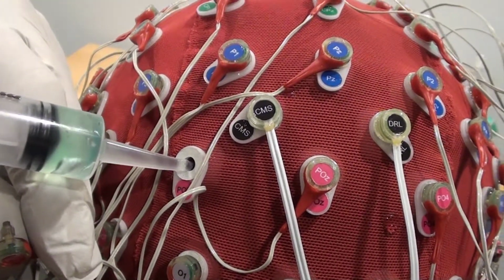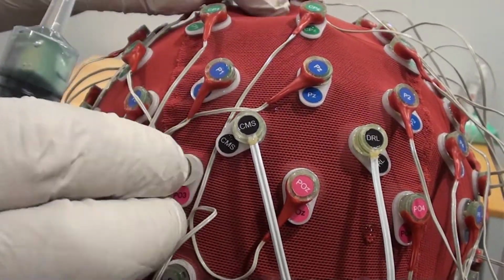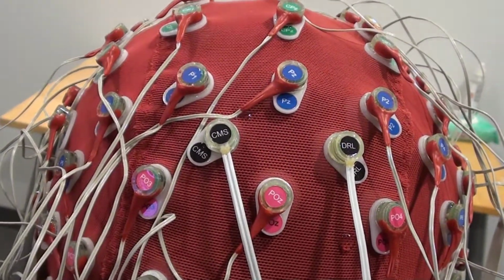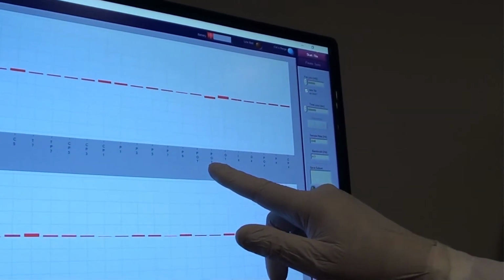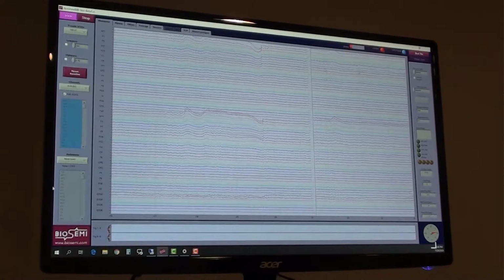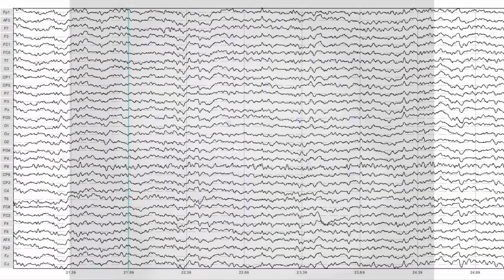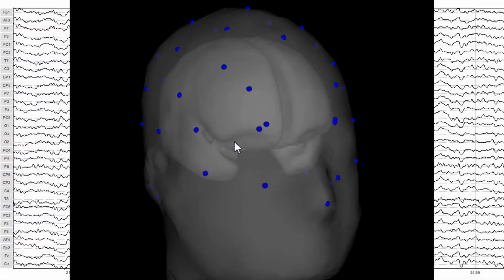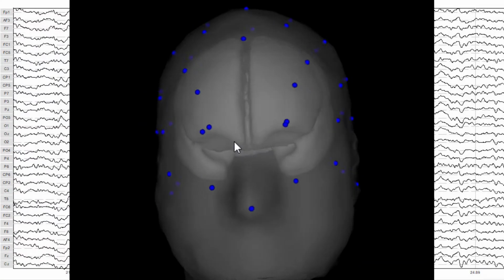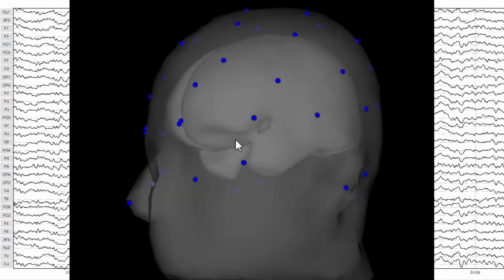In this measurement scenario, with the signal being small and the measurement device consisting of an electronic device with some cables, there's always a chance of interference pickup. How much interference is picked up depends on factors such as the design of the system, for example, modern versus antiquated equipment, and the magnitude and proximity of interference sources. So what kinds of interference sources should we be concerned with?